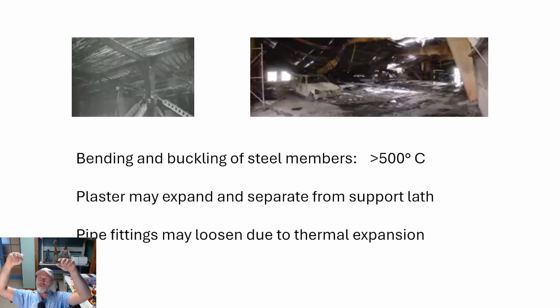So what happens specifically with I-beams is if you have a deck on top of your I-beam, let's say a steel deck with concrete above it, or basically some kind of heat sink. So that upper flange is touching something that has mass that could draw energy out of it.